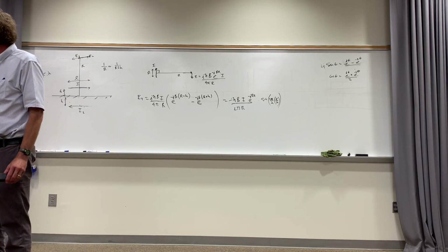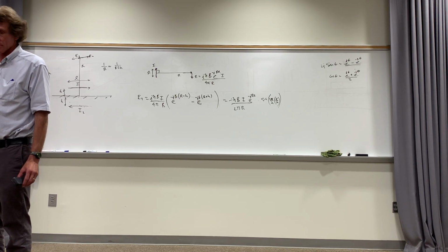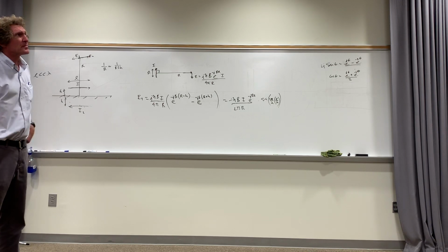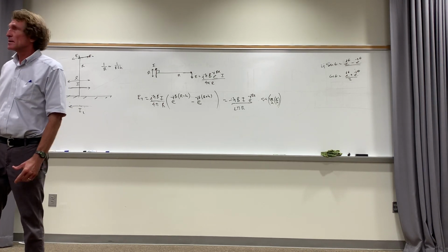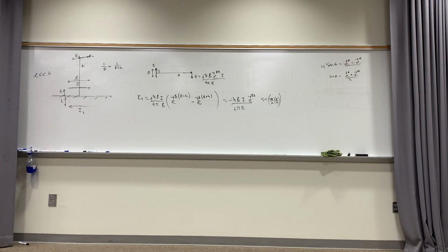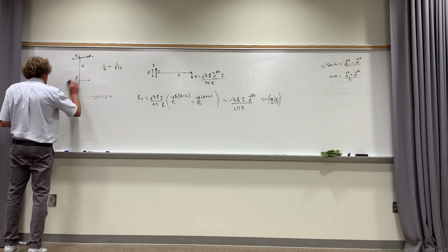Well, I can't do it here because frankly there's no exposed wires, but if I was, some of the other things, actually a long extension cord, it's not one of these coax cables. I'm talking about a real extension cord. You just lift it above a ground plane. You basically got 2 wires that are parallel to it that are imaging opposite current directions and opposite to themselves. So the actual electric field from those things can be calculated. It's kind of interesting to do something like that once. So that's what happens when you get currents that are parallel to ground planes.